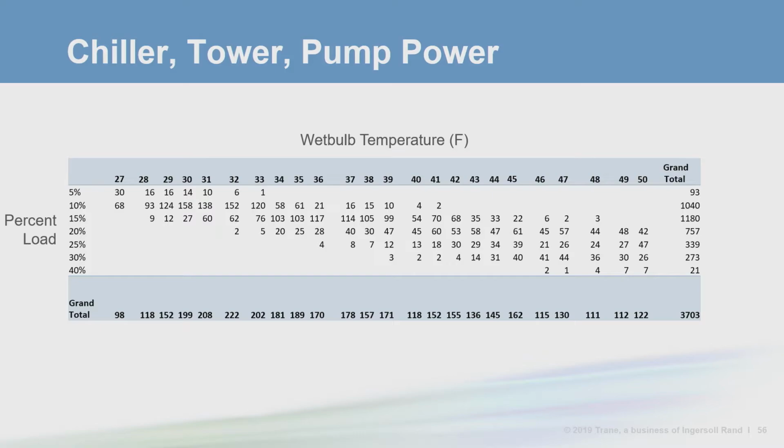performance predictions. If we bring back up that hourly data, we can see that there are some combinations that didn't exist in the model. For each column at a given wet bulb temperature, the lowest row with hours in it is the highest load expected for that wet bulb temperature. Working with a cooling tower provider, we can find the leaving temperature we can expect the cooling tower to generate. In this particular example, I assume that we have 3 chillers and 3 tower cells.